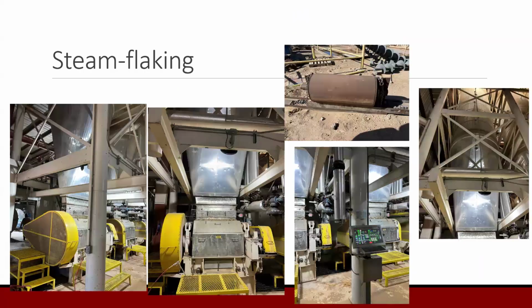I took this at the feed mill at Wrangler Feed Yards. They're by Tulia, somewhere in the Panhandle. Steam chest, roller mill. They'll steep the grain in the steam chest, it dispenses it into the roller mill, and then they'll take that grain out. Pretty much you're creating the flake for that day. Most of that flake that you're making that day will be fed that day, so they'll come in and fire this thing up prior to morning feeding.